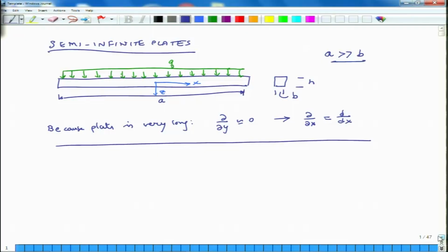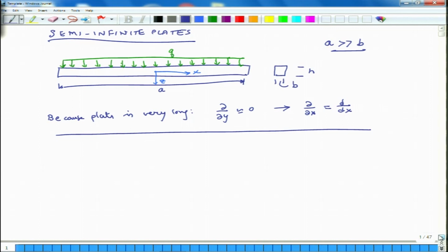And as we discussed earlier, we also need to know the boundary conditions for such a problem. So, we will have 4 different problems which we will try to solve. So, what are these 4 problems? I will just draw a schematic. So, first there is case A. In case A, let us say this is the plate and it is simply supported on both sides, but the nature of the simple supports is different. The simple support is not allowed to roll on a base at one end, but on the other end it can move.